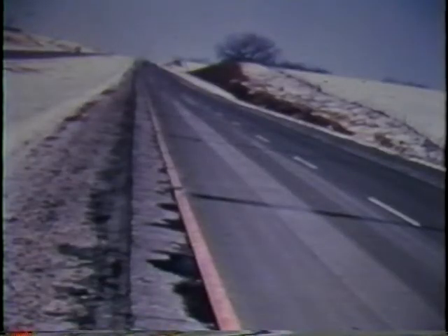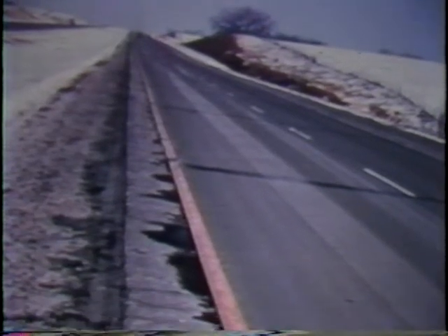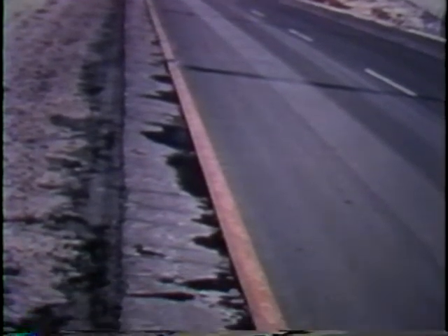The shoulder joint itself presents major maintenance problems that we need to be aware of. Separation of the shoulder and travel lane edge, as you see here, allows water to enter the base of both the travel lane and the shoulder. Excessive water under the pavement reduces the strength of the base material. Eventually, the pavement settles or breaks off. The process of deterioration is then accelerated. Differential settling occurs if the base materials are different, and vegetation will grow and cause further edge raveling.